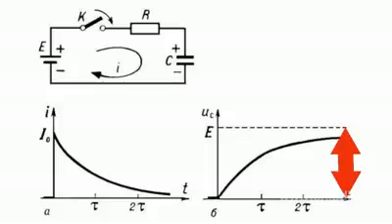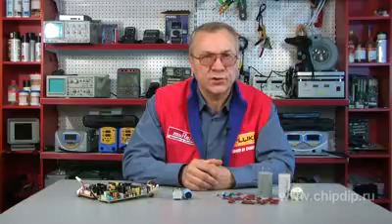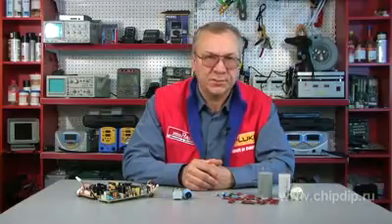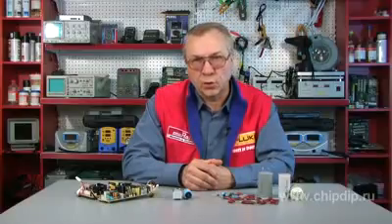When the voltage on the capacitor reaches that of the ideal voltage source, the voltage difference between the power supply and the capacitor will be equal to 0, and therefore there will be no charging current anymore. In other words, accumulation of charge on the capacitor is accompanied by an increase in its resistance to electric current. The capacitor charged from the power supply voltage acts as an infinitely large resistor in the DC circuit, and as a result, such circuit breaks.